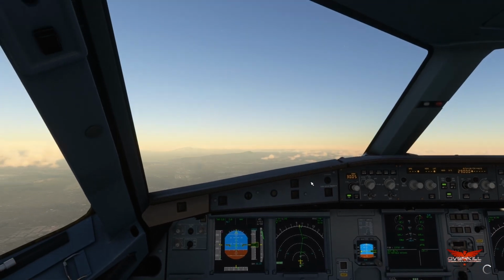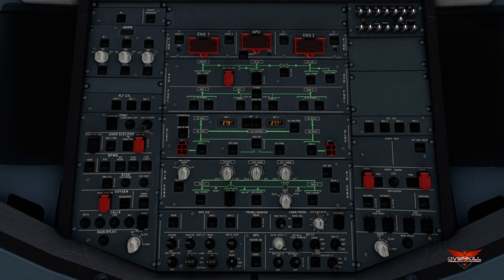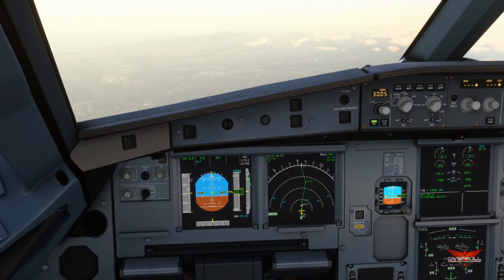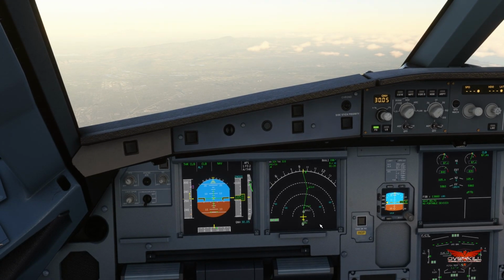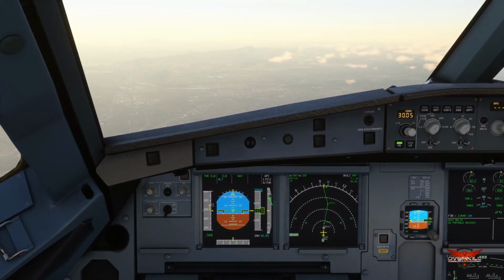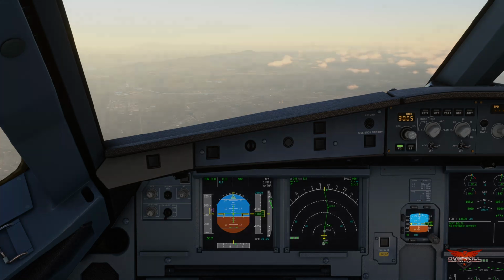All right, passing 10,000. Landing lights get secured. Runway turnoff lights could have been turned off at takeoff, but that's all right. Alright, from here we will continue our climb at 18,000. We'll hit the down arrow here on our barometer and set that to standard. But from here it's just a climb all the way up to our cruise altitude. So I'll catch you guys as it's time to start talking about our descent and holding patterns.